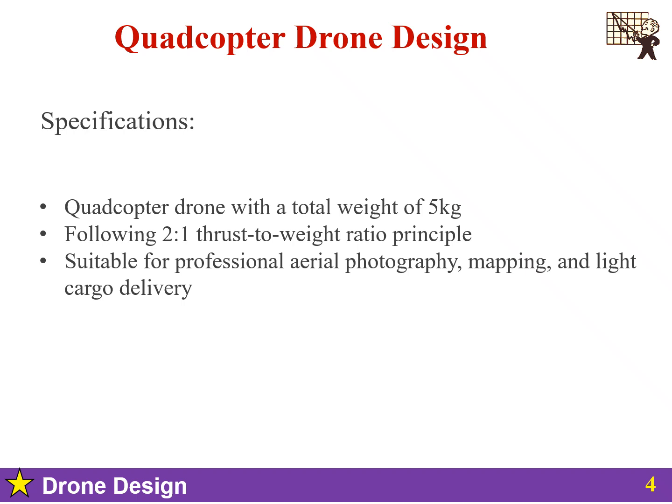First, regulatory considerations. In many jurisdictions, drones over 2 kg face stricter regulations requiring operator certifications, registrations, and potential insurance. Second, safety imperatives. A 5 kg drone falling from 50 meters carries the kinetic energy of a ball falling from the same height. Safety systems aren't optional, they are mandatory.